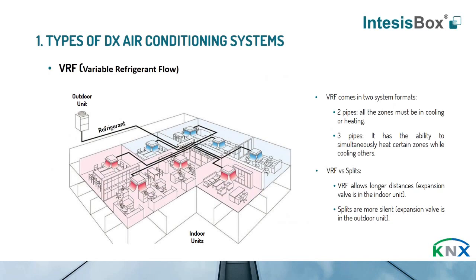So we also have the VRF system, variable refrigerant flow. You can also see this system under the name VRV. However, this is a registered name by Daikin, and other brands cannot use it, so the other brands are using the VRF name. But I have to say that the systems work exactly the same, and you can find the same solution, just under different names.